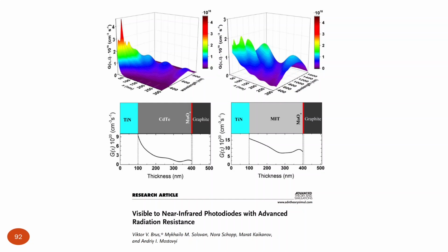First, it's good to know how we generate charge carriers inside. For that purpose, when we have a device architecture, let's say like these two here, these are also analogs of the metal-intrinsic semiconductor-metal structure with cadmium telluride and mercury indium telluride photosensitive active layers, we can calculate the optical field distribution in such devices. When we have this geometry, by applying transfer matrix simulation, we can calculate how the optical field, which means the electromagnetic field, will be distributed in terms of intensity within the active layer.